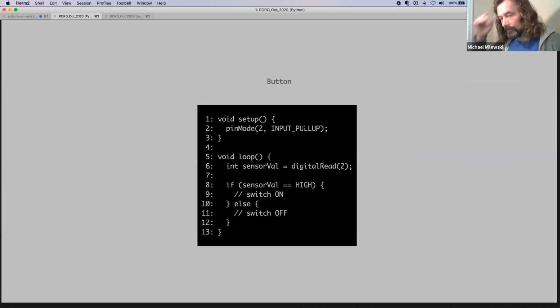Now this is interesting. One of the things about working with voltages is Ohm's law. And one of the killers is current. So if you have too much current, you can weld things together, assuming you've got something strong enough to do that. One of the things that you could do is connect ground, which is 0 volts, to 5 volts. Ohm's law suggests that if you do that with a wire or a switch, you will actually have an infinite amount of current. So it will try and run all the possible current through that connection as possible. And you could actually damage your chip, your Arduino or what have you.